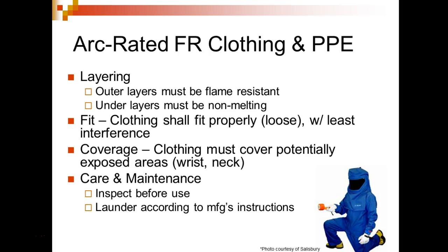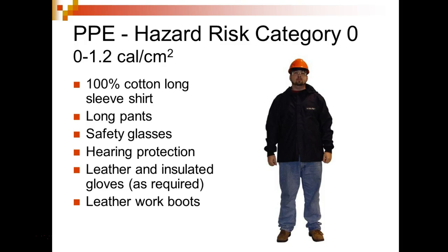We're going to try to offer a full set of this category 4 PPE. This is where we would be at. So technically, this is what you should wear. You should wear a hard hat, right? You should wear what? Safety glasses. You should wear ear protection. You should wear long pants. You should wear leather insulated gloves, but it says what? As required. And then leather boots.